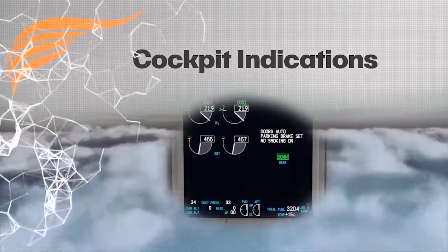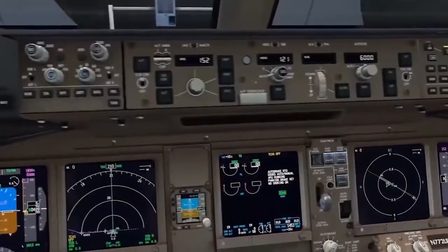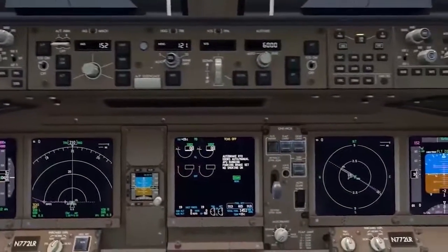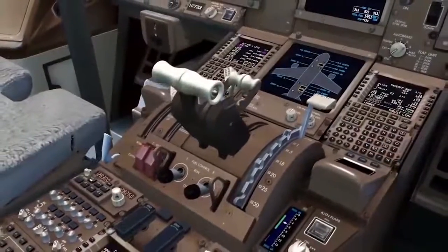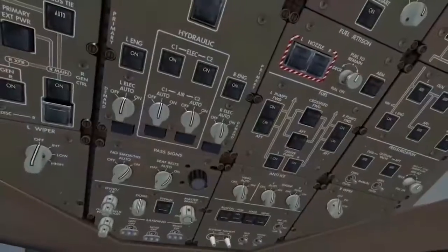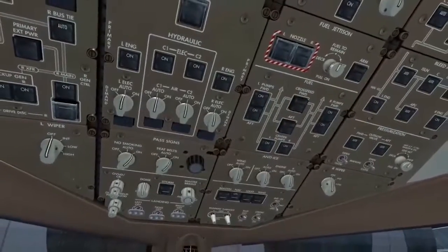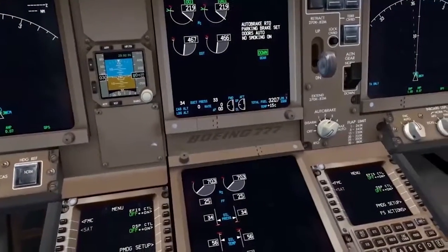You'll surely enjoy it. The 777 air conditioning system controls the interior environment of the aircraft for flight crew, passengers, and equipment. These are the system's three primary functions: control the flight deck and passenger cabin temperature, control fresh airflow for cabin pressurization and ventilation, and recirculate cabin air for ventilation.